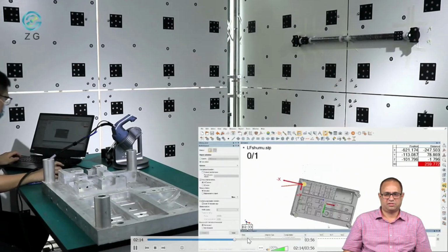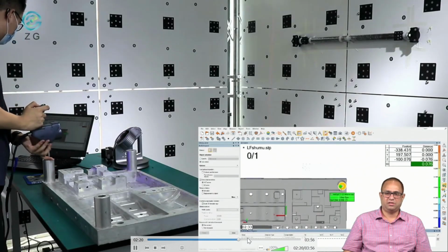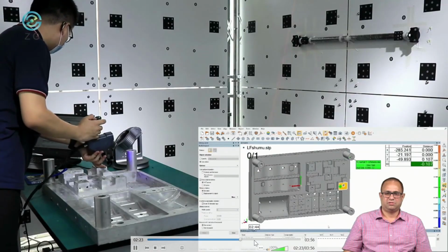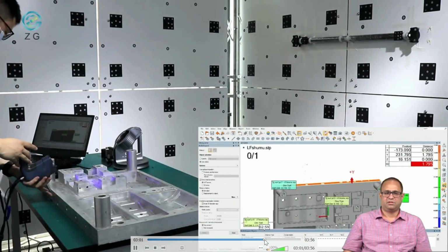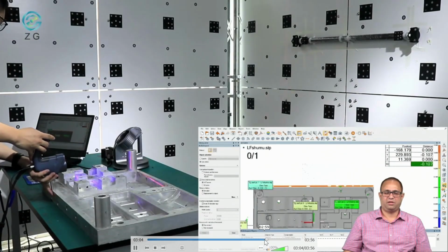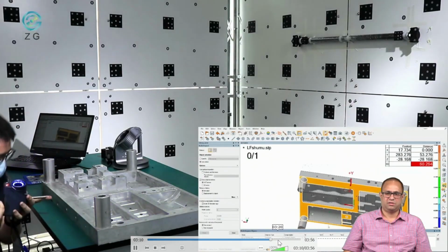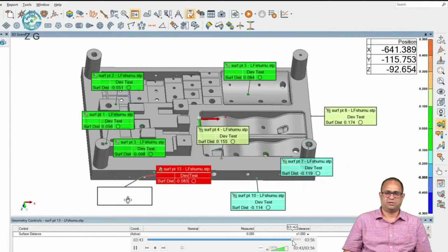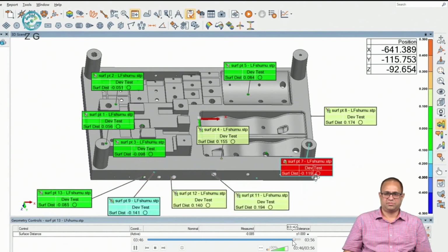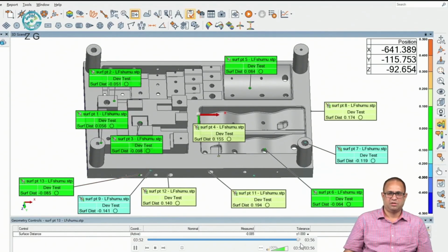You can see that all the features are scanned, and then the proper alignment, working of the coordinates and accuracy are going to be checked twice. For each and every feature, when the probe is in contact, you can see that scanning is done. Then the GD&T tolerances, whether they are maintained with the proper dimensions or not, are checked. This is called the contact type method.